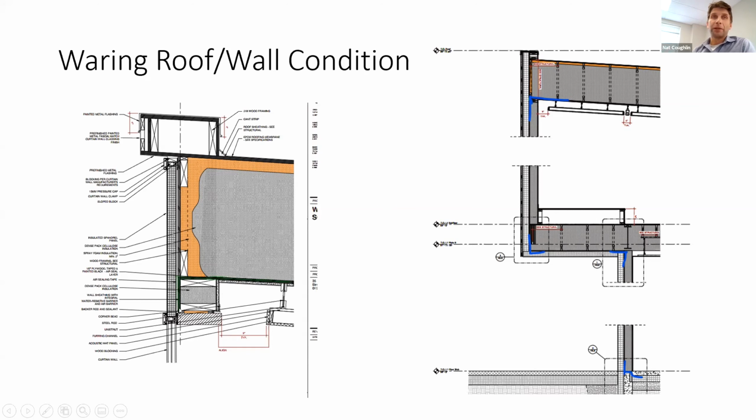Their air barrier went up the wall, across the plate under the trusses, and then under the trusses. And it let them put an incredible amount of insulation up above in those trusses, which was blown cellulose and very inexpensive compared to building up a lot of insulation on the roof. But it was really helpful that they drew it this way. And in fact, our other project also put the air barrier under the trusses for different reasons, but it was really interesting. I was not expecting that.